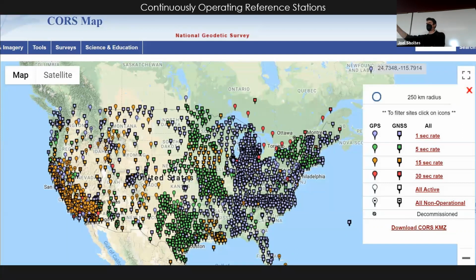they can calculate what the actual error is during the time of your survey. So error is going to change based on the constellation of the satellites, the ionosphere conditions, the weather, etc. And so when you do your survey, they know what the general background error is, and then they can update your accuracy point by point.